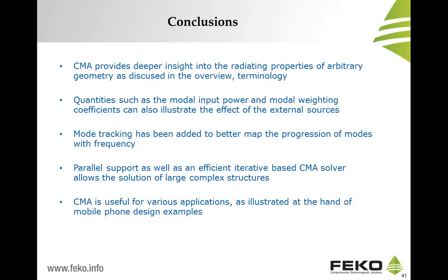Now, in conclusion, I would just like to summarize by saying that characteristic mode analysis provides a designer with deeper insight into the radiating properties of arbitrary geometry, such as those that are discussed in this presentation. Quantities such as the modal input power and modal weighting coefficients can also illustrate the effect of the external sources, such as I explained with the mobile phone example, and also the simpler dipole example.